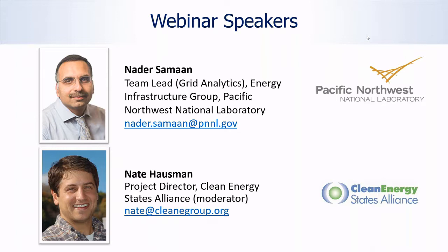That's why our approach is to take day-ahead data, the best forecast we have of PV and load, and put it in our planning case that represents the feeder distribution system model. Based on that, we come up with, say, 24 values of power factor or active power dispatch for the solar plant, and send this to the solar plant owner, who will change their active power each hour according to our analysis.